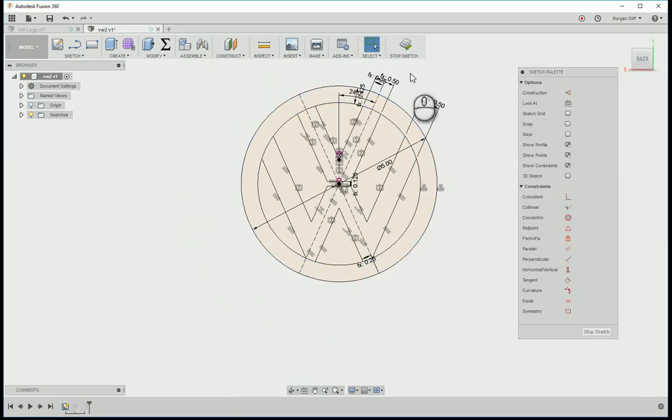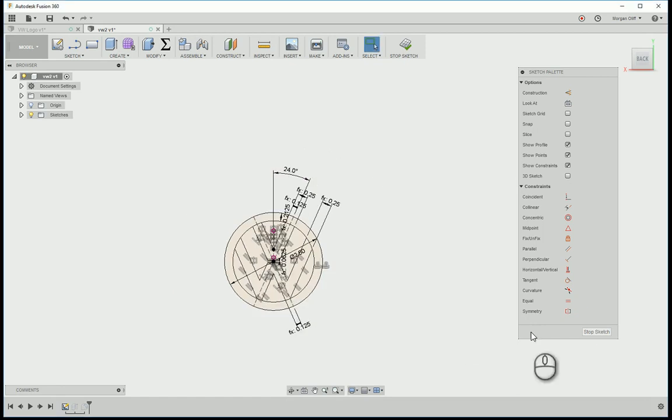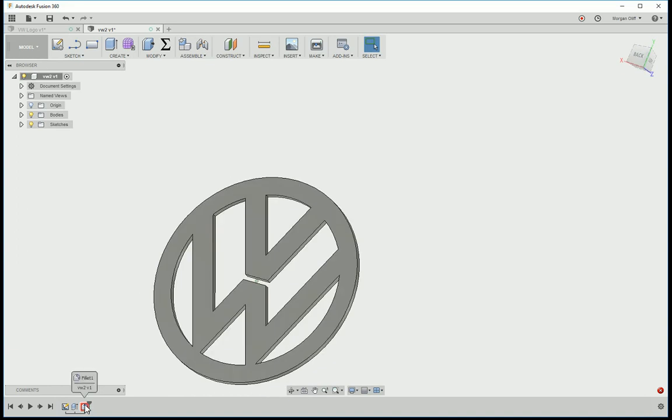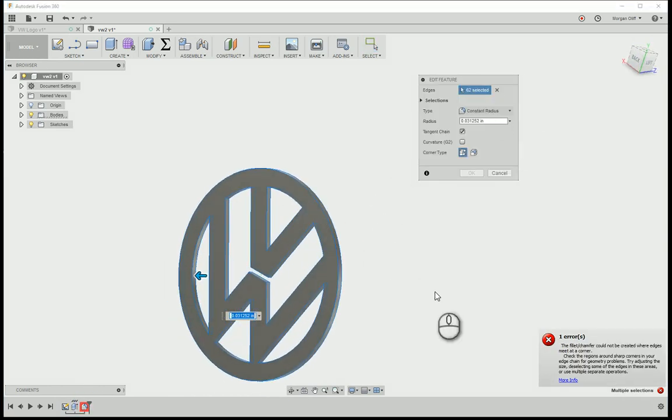So say this is sitting at 5 inches. Oh, it was calling up, when I saw the 2.5, it was a radius dimension. So let's say if I make this 2.5 inches, it's going to scale down. And our fillets are unhappy. It's because that's too much.